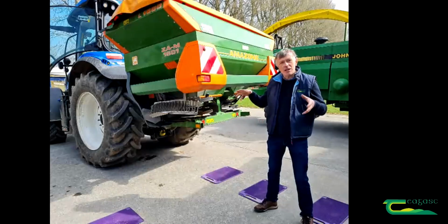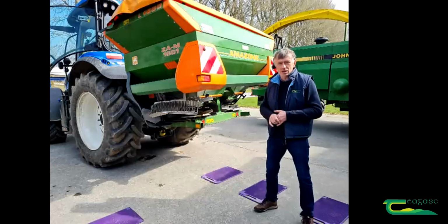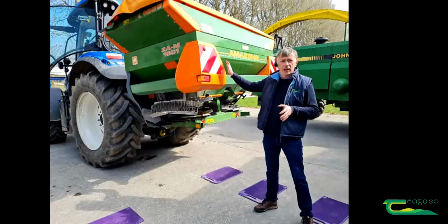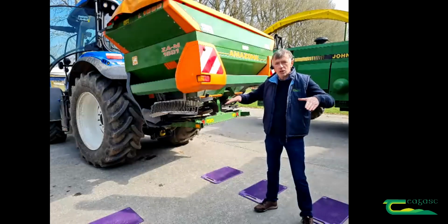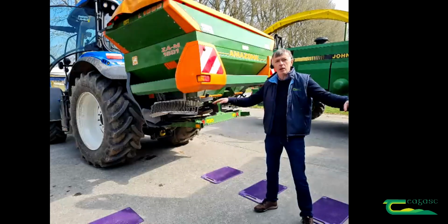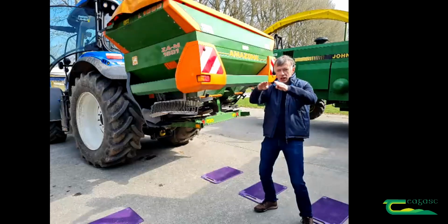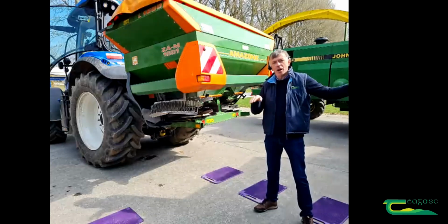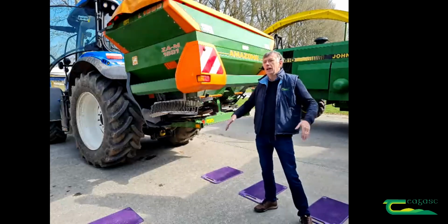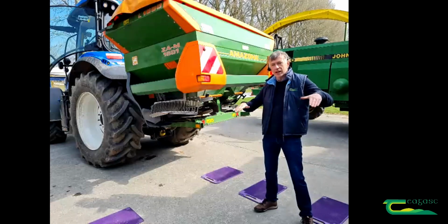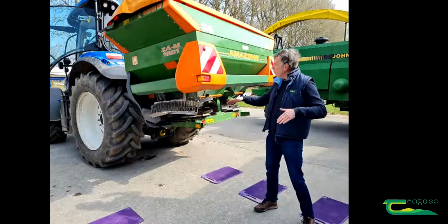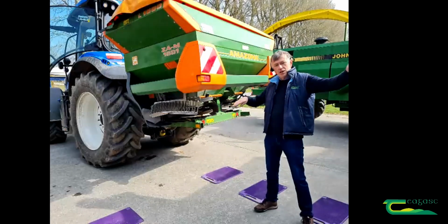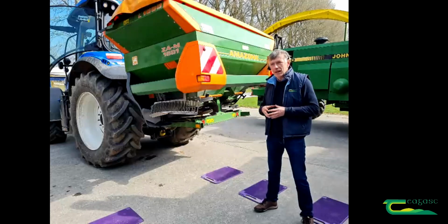Some of that is down to the setting of the machine, some of it is down to the design of the machine. Because when you think about it, all of these spreaders are broadcast spreaders. A good spreader will spread really wide and overlap the pattern, so it has a taper pattern, decreasing as you go further away from the tractor. That's compensated with the next run of the spreader by matching up with that, and that gives an overall even spread. But when we're spreading on the headland, we're doing the opposite. We're trying to get it to spread a full rate out to one side and then suddenly to stop. So it's a big ask.